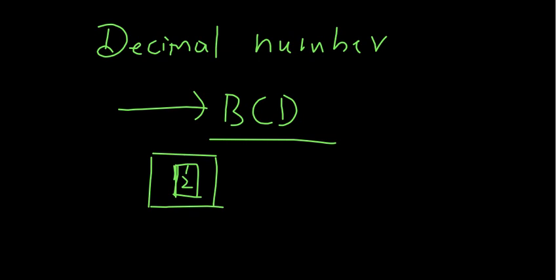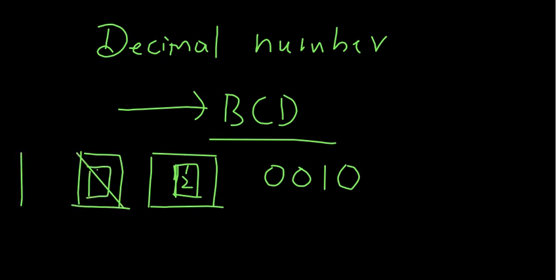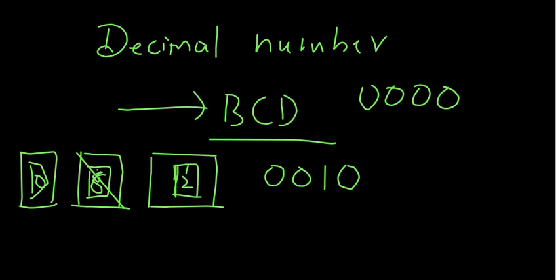As long as I measure a temperature of 35 degrees centigrade, I should be able to represent this 35 degrees centigrade, and accordingly it should be compared with some preset number to identify whether it is equal to, greater than, or less than that. So the basic representation of a decimal number will be in the form of binary coded decimal, like any other kind of digital devices. But even though you represent them in binary coded decimal, you must have some instructions to handle this data.